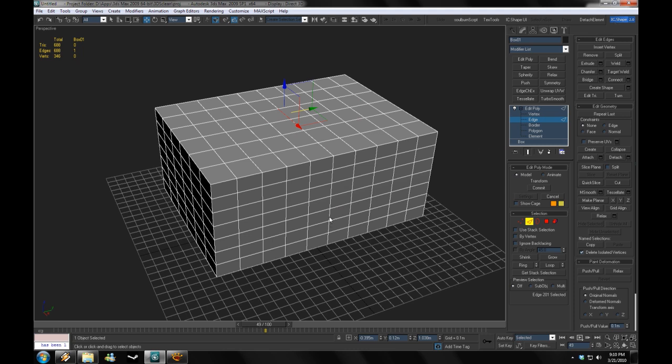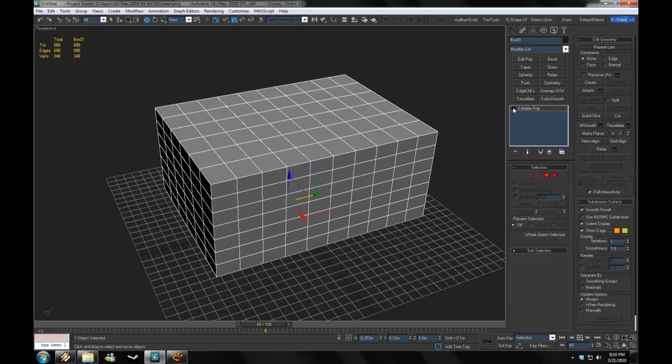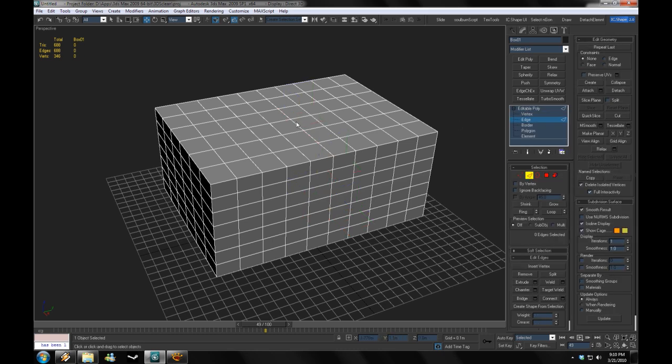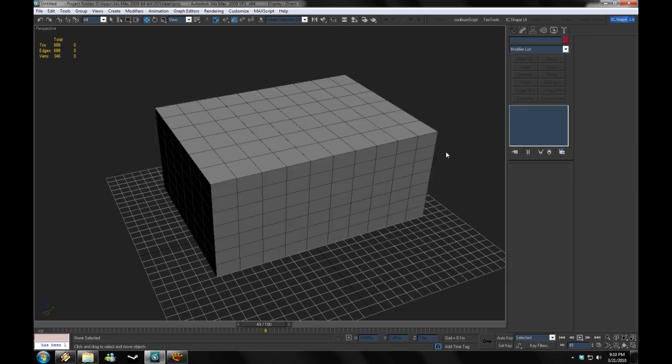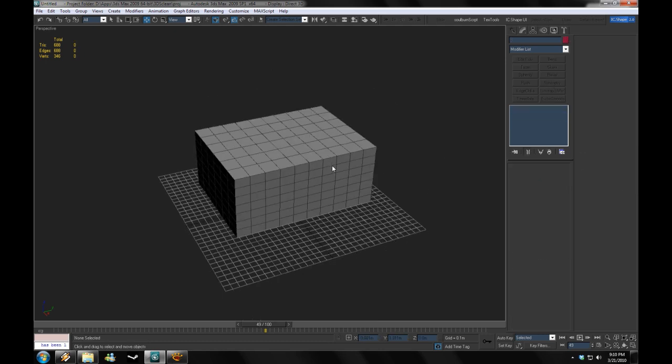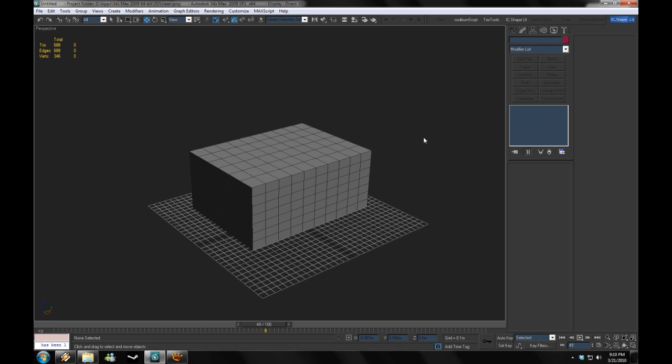It allows you to select the start and end of an edge loop, and then you can press a button. I have it set to Control Q, and it'll automatically bridge the gap between it and select all the edges between those. Very useful. Allows you to quickly select just a small region of an edge loop or edge ring. It's kind of buggy, but it does work most of the time, as long as you don't have any modifiers on top of it.